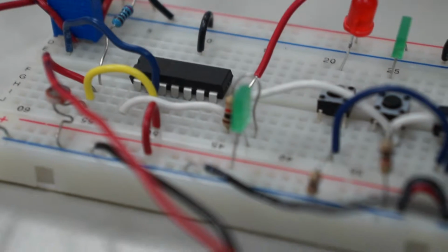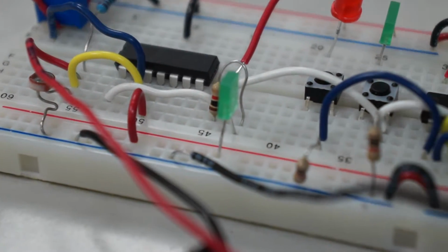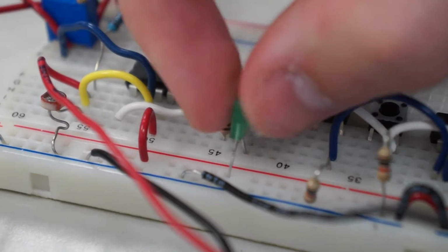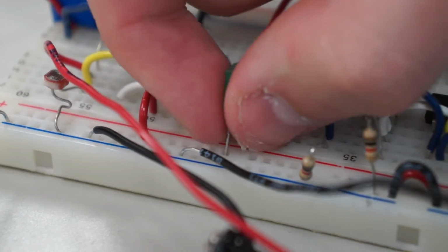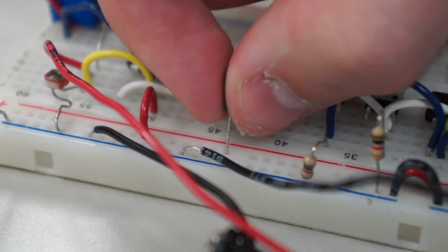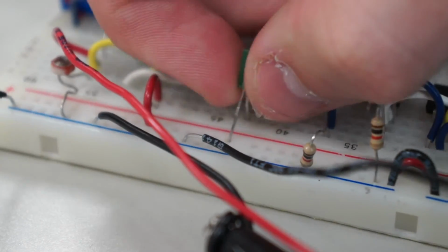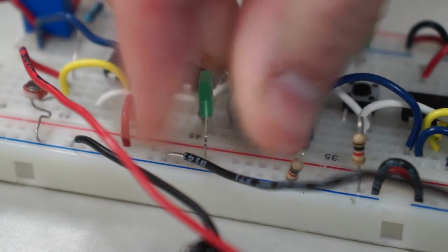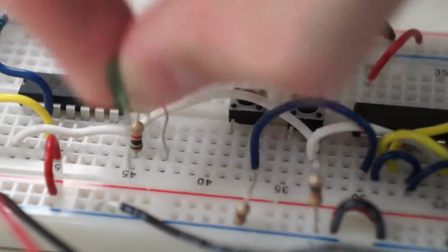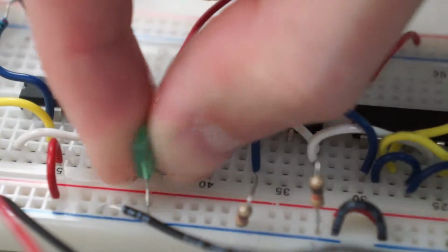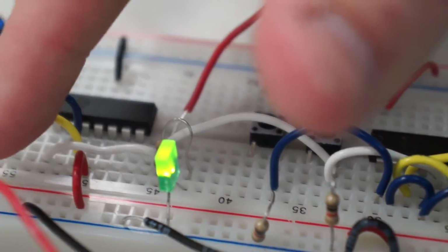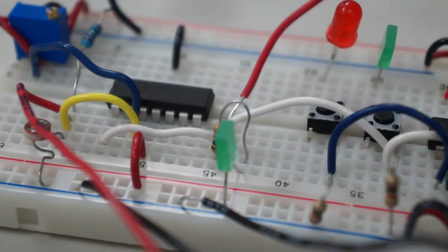We look at our schematic and we can see if everything's plugged in correctly, and then we noticed that the LED is plugged in incorrectly. It's plugged into the power line and it should be plugged into ground. So by fixing it and plugging it into ground, this should fix our problem. And now subsystem 1 is correct.